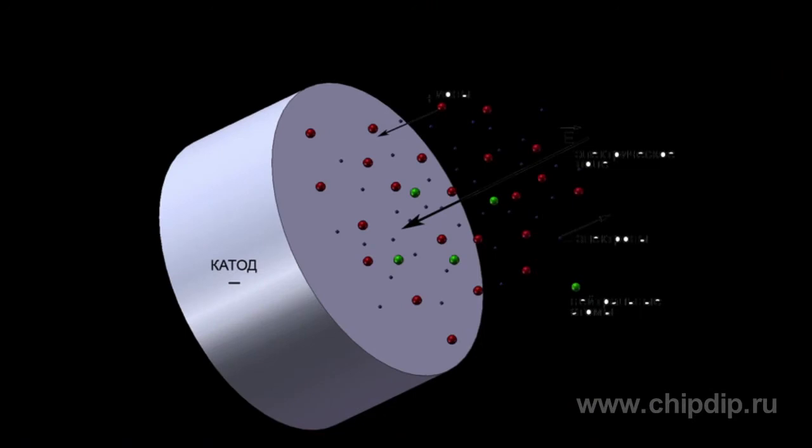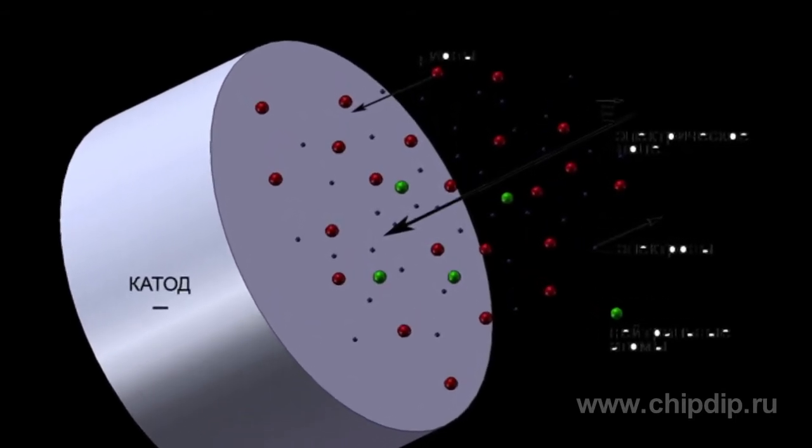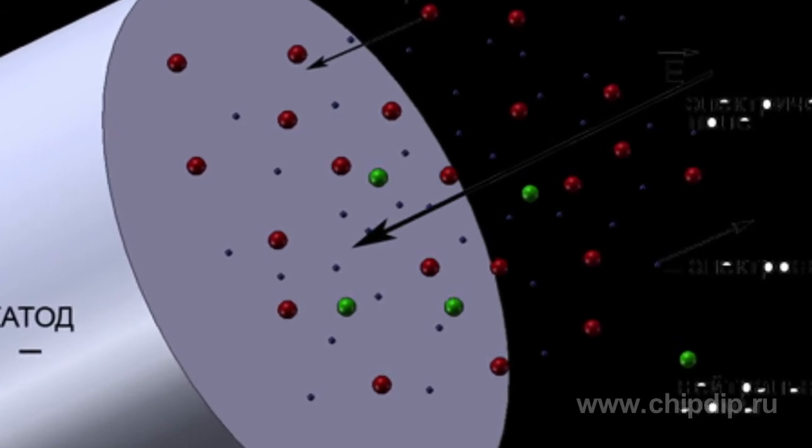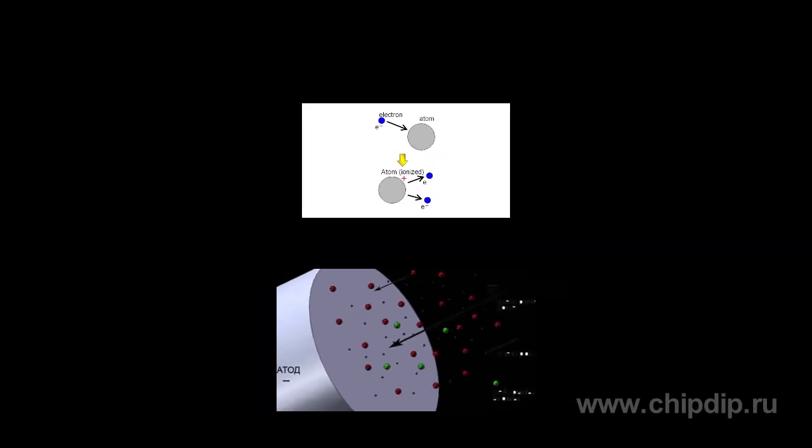The mentioned properties of glow discharge reflect the following pattern of discharge-maintaining processes. Positive ions are formed as a result of the electron impact ionization in the glowing fluorescence and the positive column. The ions move towards the cathode. Having passed through the region of the cathode potential drop, the ions acquire a considerable amount of energy. Electrons leave the cathode influenced by the intense bombardment by high-speed positive ions and the photoelectric effect caused by discharge emission. The electrons move towards the anode.